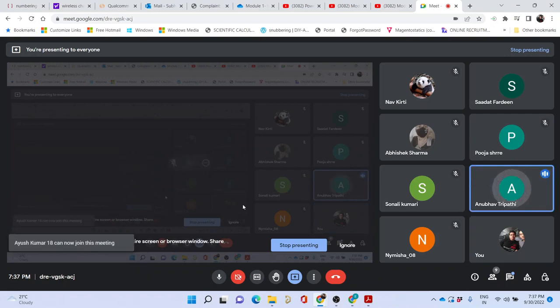Sir, I didn't consider the zero. So the angle of asymptotes becomes 90 and it approaches infinity. I just solved by taking the frequency, putting minus omega square plus k equal to zero.